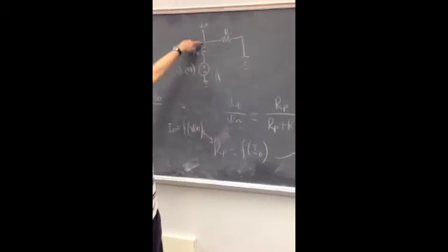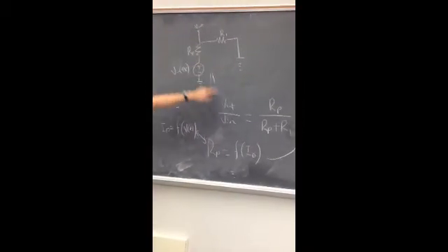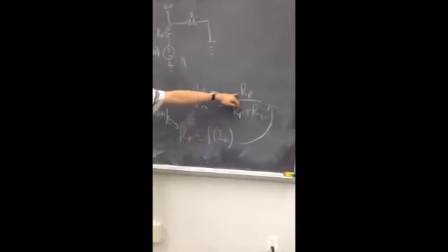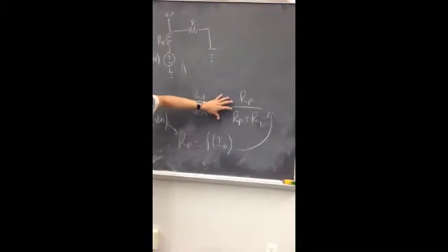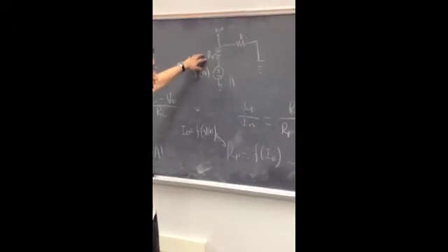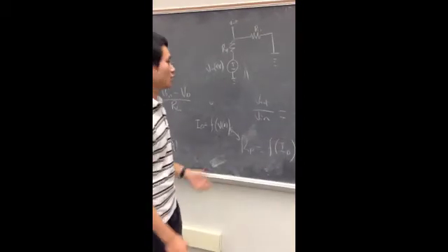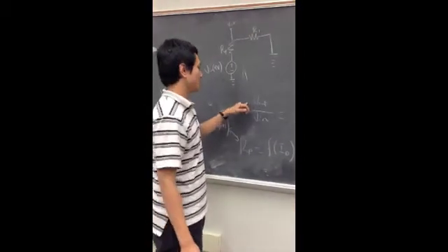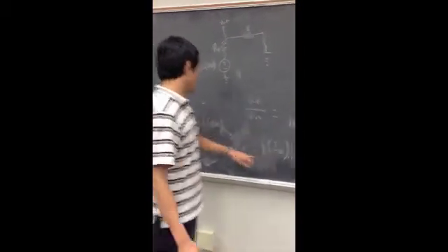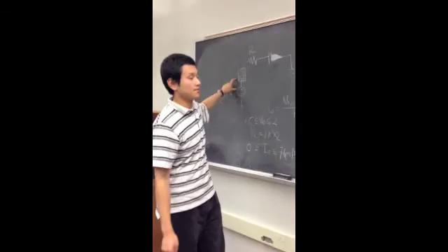Therefore, from here we lead a V out to the speaker, and that V out is sort of governed by this voltage divider, which takes the resistance of the photosensitive resistor over the total resistance across this whole circuit. So as this varies, the V out over V in varies according to the original sine wave coming from the iPod and the battery.